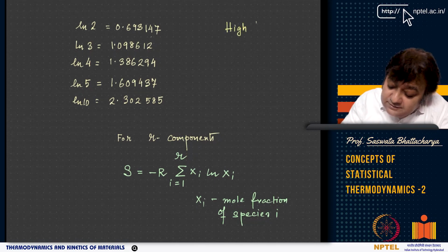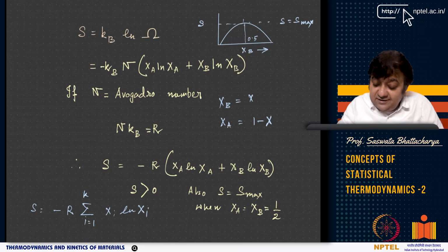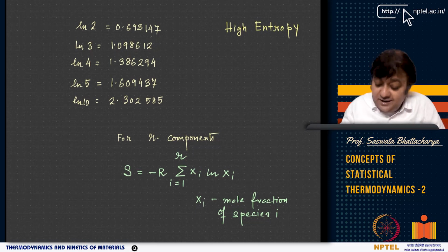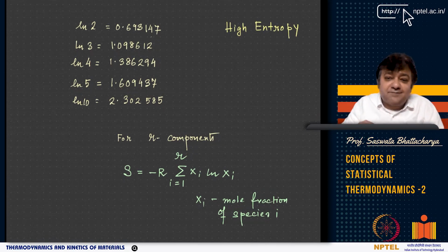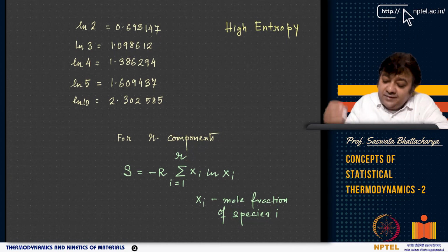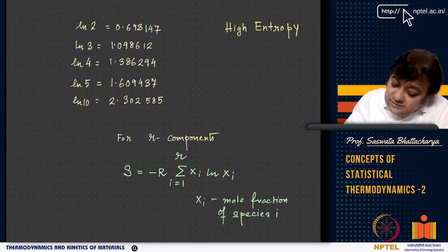Many of you have encountered such names, where you basically mix a larger number of elements, like 5 elements, in equal proportion. Why equal proportion? Because as I told you, when it is 50-50, it has the maximum entropy. Similarly, maximum configurational entropy, right? Because we are looking at entropy here from the standpoint of configurations, the maximum number of microstates that corresponds to that macrostate which is likely, and that macrostate is going to determine the entropy, right? And that is always going to be the distribution where you have an equal number of different species, right? So this is called the high entropy alloy concept.